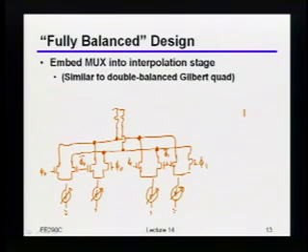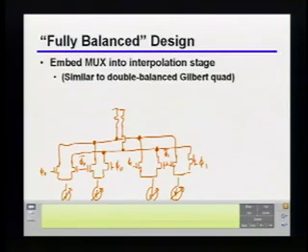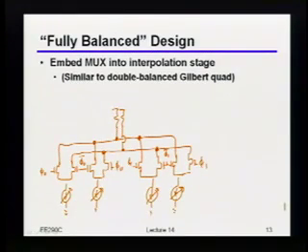Okay, great. So actually, that's the end of the practical issues with normal phase interpolators. Okay, so, if you do something like this, or in fact, you don't necessarily have to do it all directly at the output. You can, in fact, do things where you just have one big mux and then feed that into the buffer stages. That also works fine. But indeed, this is a fairly common way of doing things in terms of phase interpolators.